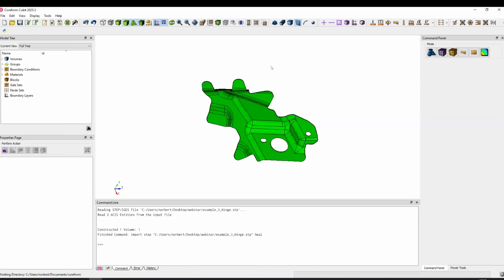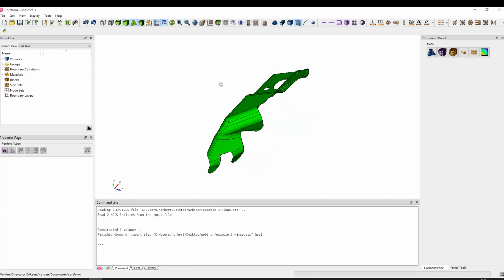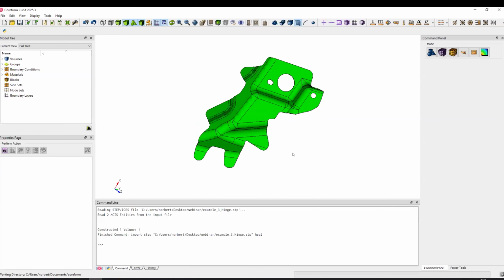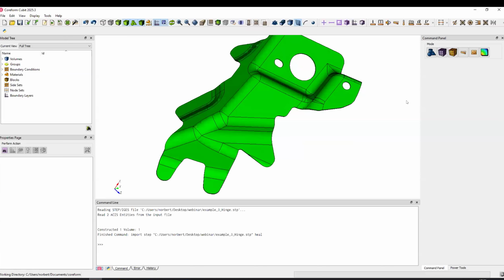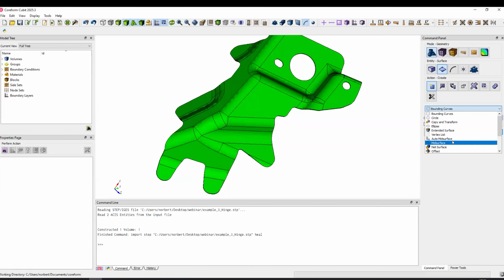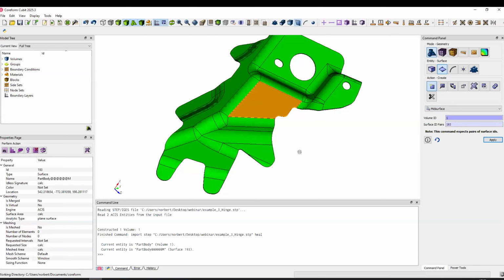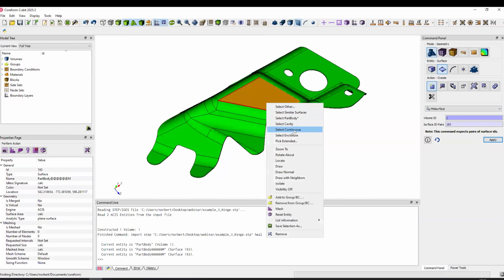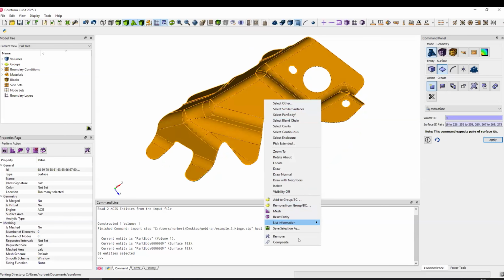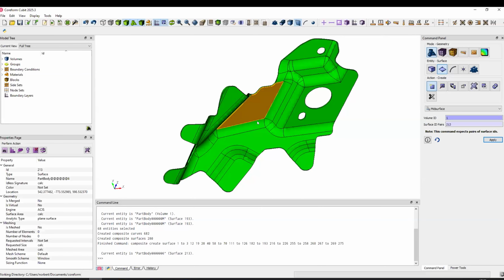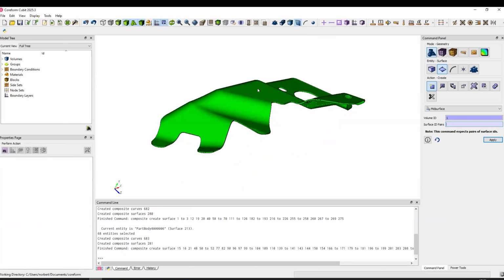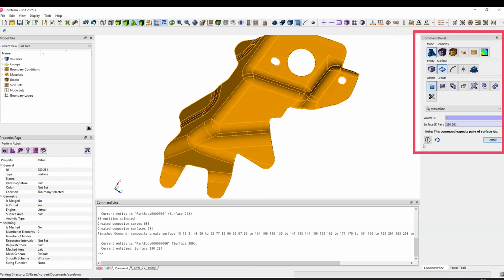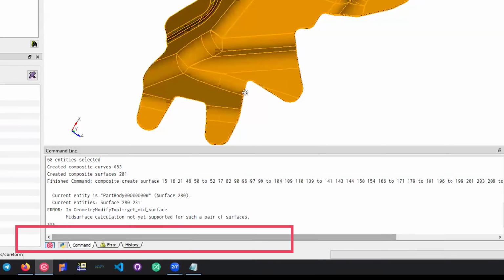That's basically a sheet metal part. And if I want to get not a hex element mesh for this, but a shell element mesh, I would need to mid-surface this geometry. Usually when it's a simple geometry, I could just say, okay, create mid-surface, get me some pairs. I don't have a single pair, so I would probably just select top surfaces, make a composite, select the bottom surfaces, again making a composite. And then I could just choose the surface pair and say, okay, please make me a mid-surface here. And I will run into an error.